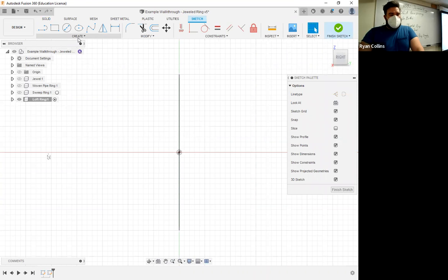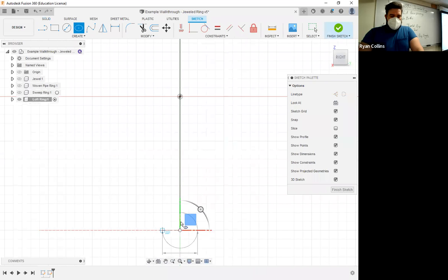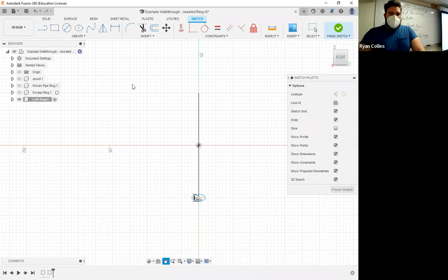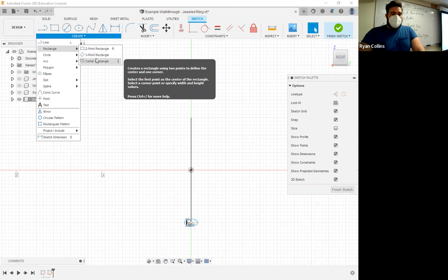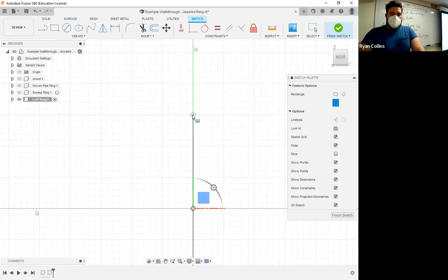So with this one, let's make something that I can have something to work with. So I'll do an ellipse at the very bottom, snapping to the center bottom. Let's say, sure, 4 and up to 2. Okay. And then at the top, let's use something more rectangular, like a rectangle. Center there, snap to the middle. 2 seems reasonable. Let's make it a little bit wider, 10.